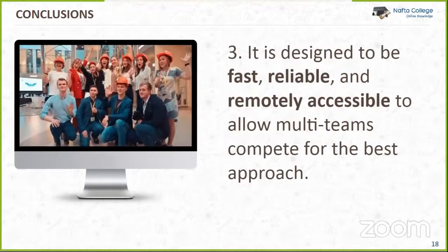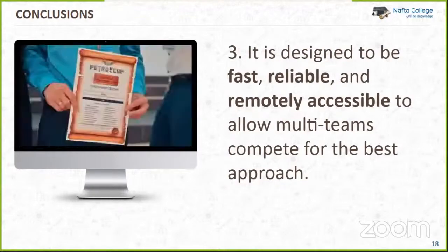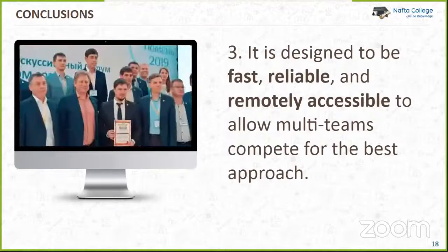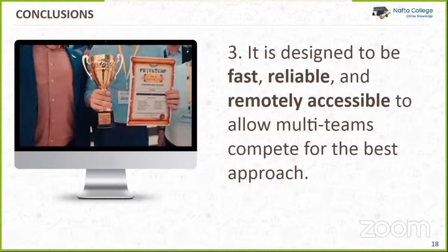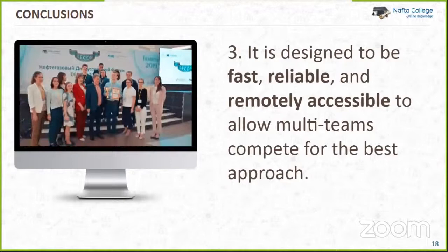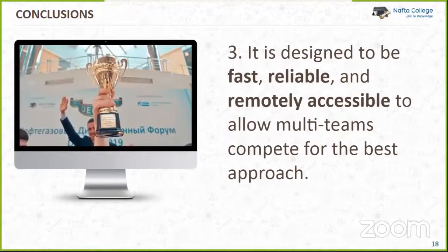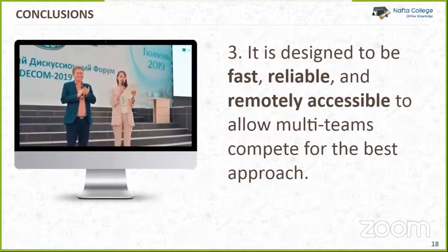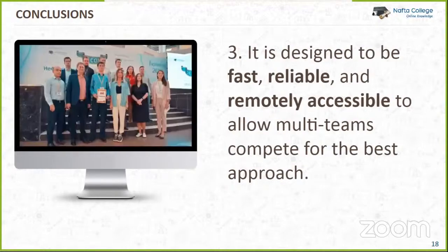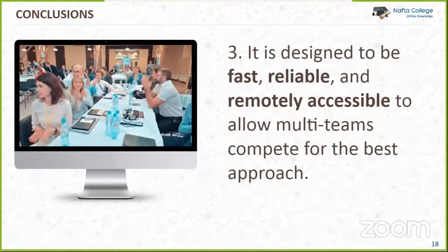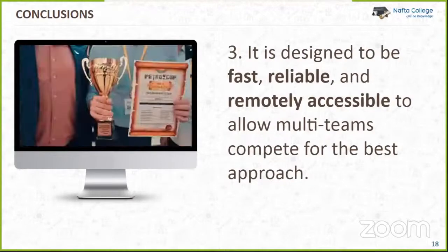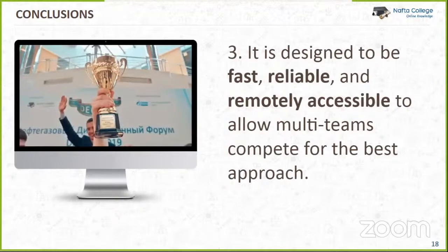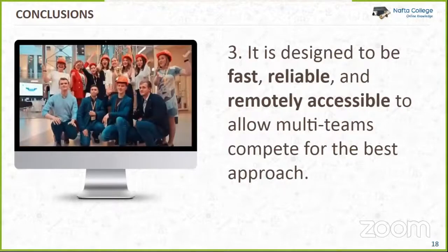So I strongly recommend spending some money on finding out with the PLT, the production surveys, flow meter and noise log, and to find out really where and how much of it, quantify it: temperature, noise log, production, and the flow meter. If you can get those in combination, it will be money spent, very good money spent.